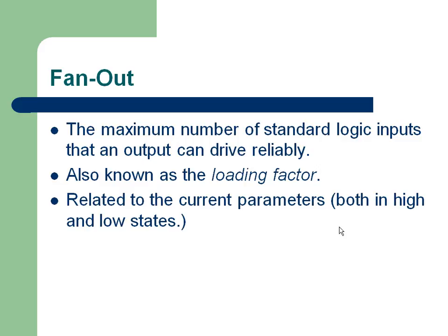Okay, in digital circuits, the clock is the most heavily loaded signal. Why? A full adder or half adder has inputs A and B, and the output of the full adder goes to some other circuit. So an ordinary signal may go to only a few gates. But the clock goes to all the registers. So the clock should be the signal with the highest driving capability. That is why people talk so much about ASIC clock tree insertion and clock tree management.